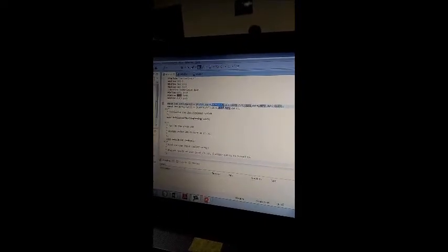and this is the table form that we control each of the LED 1 to LED 6, and by default it should be none, which is 0, 0, 0, creating all as input. So this will be the coding that we use this time. First we declare the switches and we declare the outputs. Then we use a table method, which is an array, to set the output following these patterns. Let's say this is the 0, this is the 1, 2, and so on. Same goes for port high, output 1, output 3, and I will explain this later on.